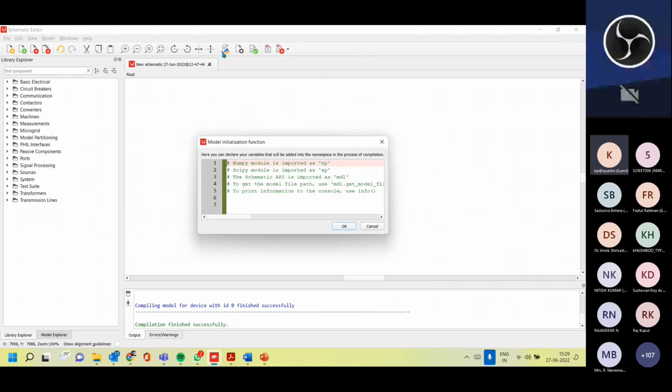And here is the model initialization. When you go through the hands-on parts, if I would like to give some values and don't want to insert them in the model, I just want to make a direct change from here. So I can insert things like the simulation time step. I just give it here, and if my results are not coming or for filter values, I can give it here. So I will directly change it from here and compile again, without going into the component part.